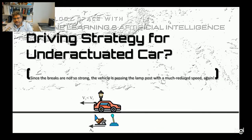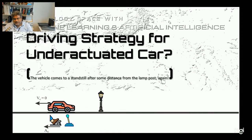Since the brakes in this vehicle are not so strong, there's a possibility this vehicle may pass that lamppost at a much reduced speed in this situation. I'm referring to that speed as V5, and it has the same deceleration of AB. Then again this vehicle may come to a standstill after some distance from the lamppost, but this distance may be less than the initial location of the vehicle.